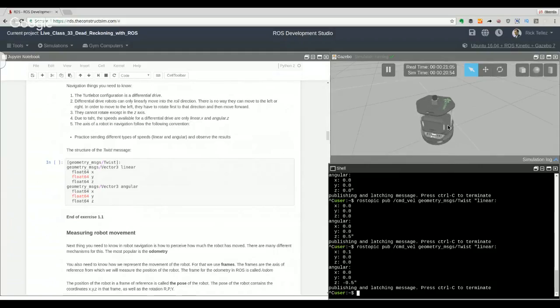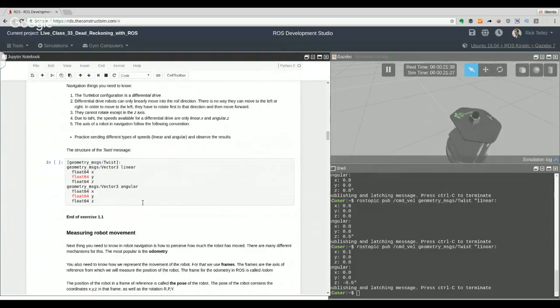How can you implement this? Well, very simple. You can create a program that is listening to the cmd_vel, and if it detects that somebody is publishing a speed on that topic at a certain rate, let's say 10 hertz, then you do nothing. But at the moment that you detect that more than that time has passed without anybody publishing there, then you directly publish a 0, so you can stop the robot. That's a safety measure. Okay, let's go.